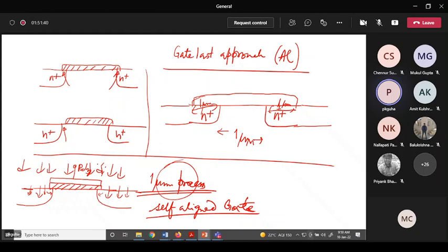But what this will do, you see now, even if this is my 1 micrometer process, this part I am not achieving through lithography. This is automatically happening because here the gate is acting as a masking layer, and while diffusing or ion implanting those phosphorus or boron ions, they not only move vertically, some of them will also move a little bit horizontally, and give us this tiny overlap which is good enough to achieve that overlap actually, right?